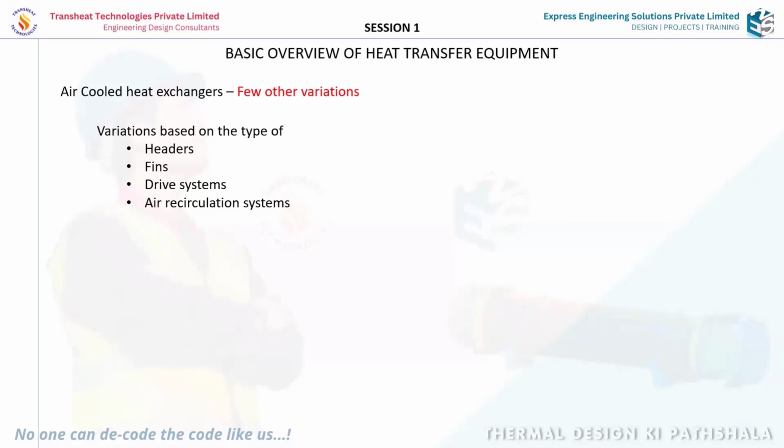Then we always hear the word air cooler, where we are saying that the process fluid is cooled by using ambient air. So we are using air to cool, so we call it an air cooler. But there are instances where ambient air is also used to heat another fluid. This is particularly the application when you talk about large LNG stations, where the process fluid is at a much lower temperature and needs to be heated up before it goes into your distribution network.